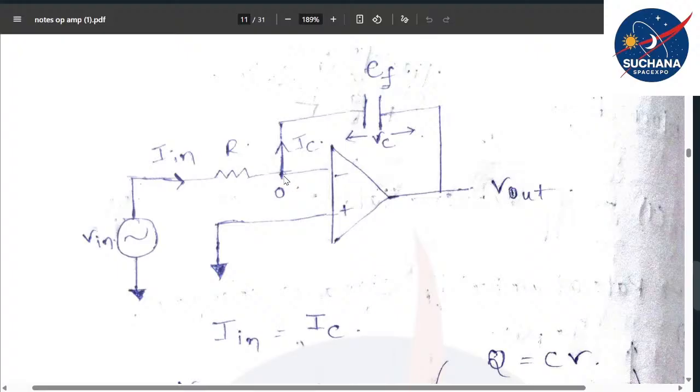So here what is actually happening is, in this particular circuit diagram, I have connected the non-inverting terminal to the ground. Okay, is this clear? Do you agree? Yes. This is another way to represent the ground, just a triangle. Now what I am saying is, in this specific scenario, when I tie this non-inverting terminal to the ground, the voltage at the junction which is formed between the negative feedback loop and the inverting terminal is 0, because of the virtual ground concept. This particular node acts like a virtual ground.